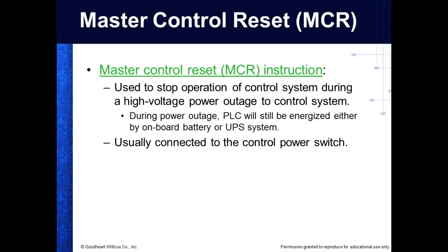By the way, MCRs are not supposed to be implemented with a soft switch. The switches have got to be contact switches, right? You understand that? They actually have to be like a push button, like an e-stop or something like that. So they can't be soft, they're not supposed to be, I'm sure.